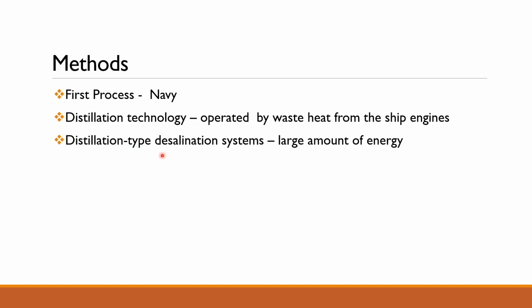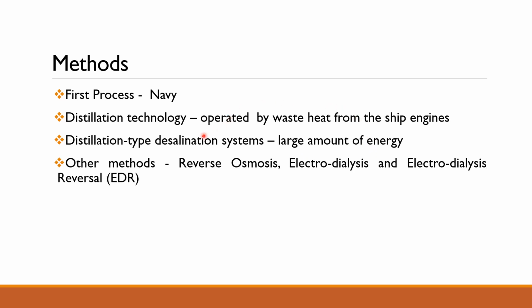This distillation type desalination system works well, but it has one major disadvantage, that is you require a large amount of energy for vaporizing the water. That is why you have other methods which do not require as much energy, such as reverse osmosis, electrodialysis and electrodialysis reversal.